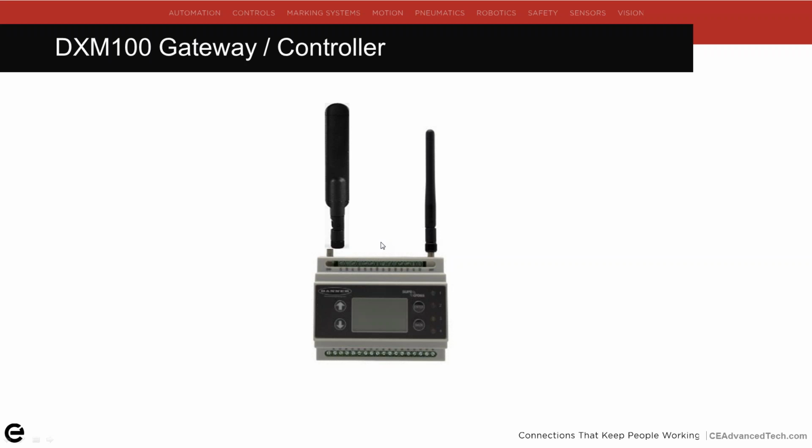So the Banner DXM can communicate, and today we're communicating just straight Ethernet, getting a DHCP address or even a fixed address from my local network and traveling on out to the internet. No public IP address is required here. Also, though, I can use a cellular card and go direct cellularly.